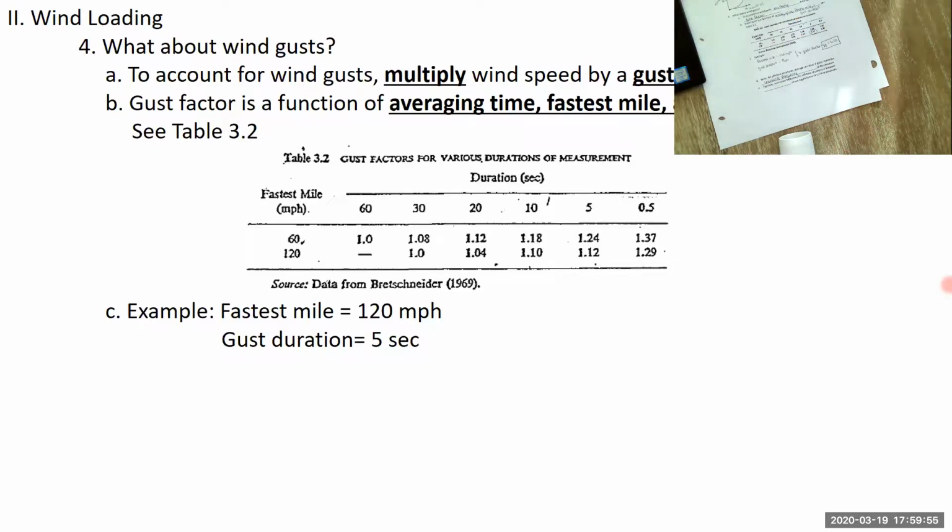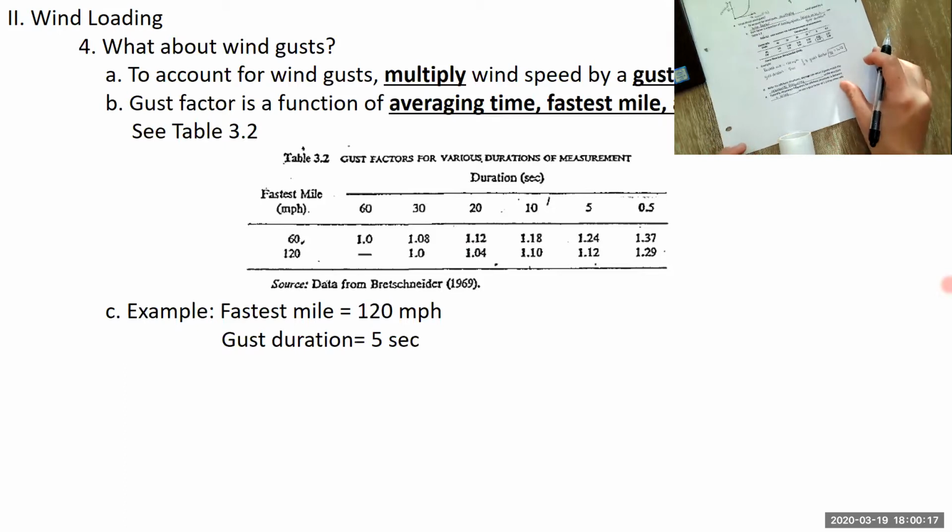Similarly, if you have gusts offshore for your offshore structure, you might have a similar effect if the resonance frequency matches the frequency of the gusts. Typically, the resonance frequency for offshore structures is between 1 to 10 seconds. And so if you don't have any other info, it's conservative to use a factor of safety of about 1.2. But again, if you do have more info, it's better to use that information.